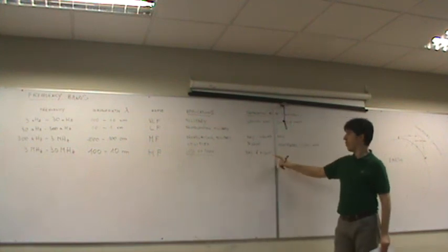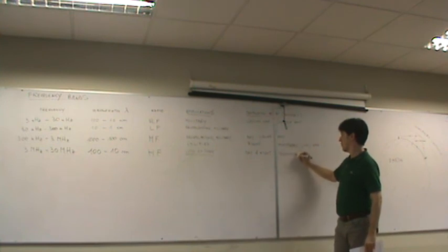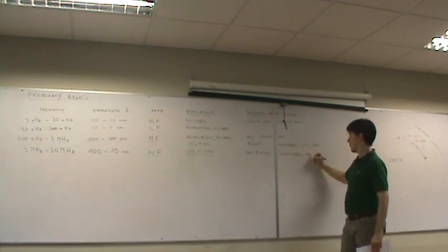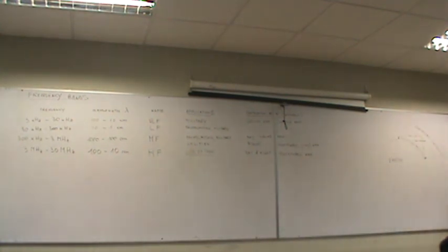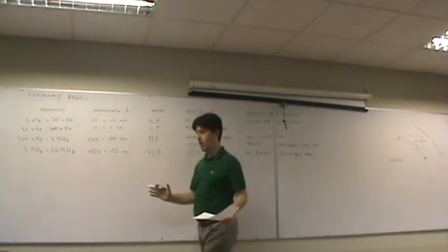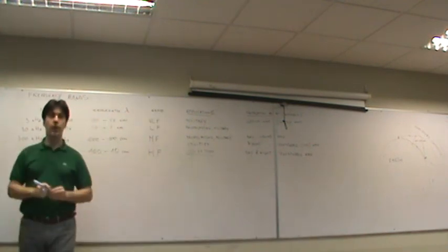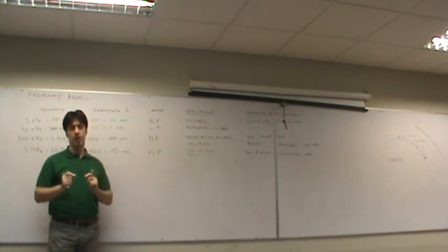Because the dominant propagation mode is ionosphere. It means that depending on the condition, you can find frequencies that can bounce back. Actually, they can make multiple bounces, and you can have a global coverage. You can actually communicate with any point on the planet with a proper choice of frequency and time.